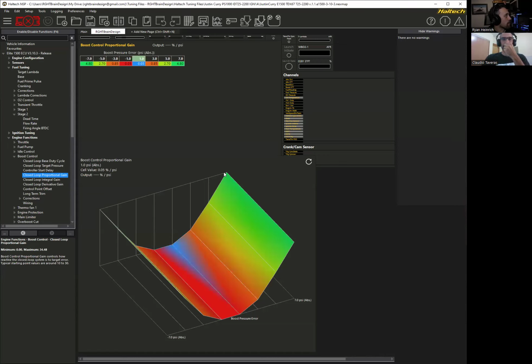And then this is just an arbitrary speed, and these are really not identical from ECU to ECU. So play with it, you'll figure out what works, and from device to device, each piece of hardware requires different control. It's the same with injectors. Each injector is different. Each coil is different. So each device, each feature will require attention to the PID that it requires.